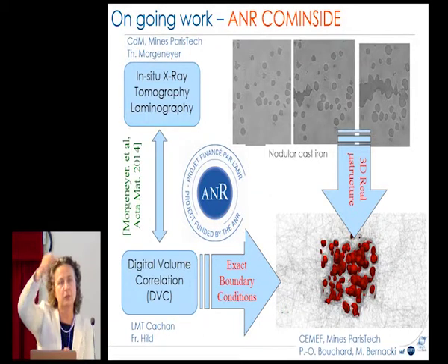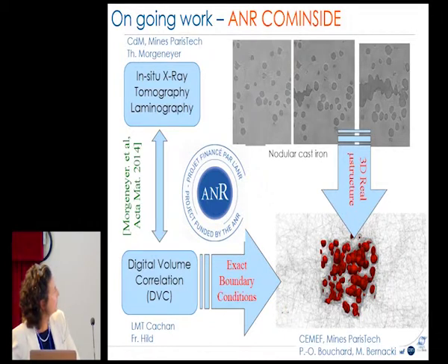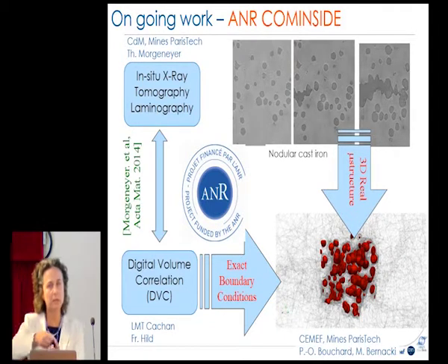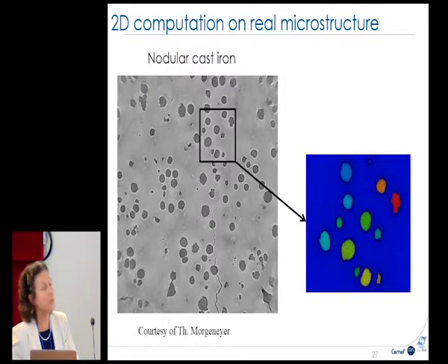So we make, for example, this tensile test. We have one inclusion with a fracture here, and here it's a different inclusion in this direction. We make a tensile test in this direction, and we propagate the void here due to the fracture of the inclusion. So you can see that, it's difficult, but the void is meshed, that we mesh this zone too.